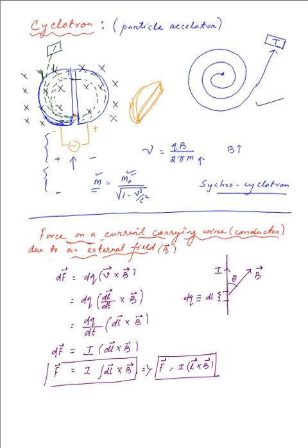So this is another form of that QV cross B that we had discussed earlier. In this case we are considering the length as well as the current that is flowing through it. So the same thing interpreted in a different manner with the conductor and its parameters available to us. Now we had discussed QVB. Let me add a term which I hadn't added previously because we were not involving the electric field over there. So now is the time to use that term, which is known as the Lorentz force.